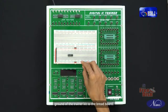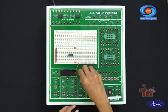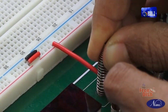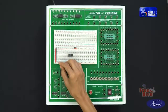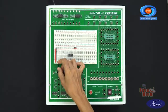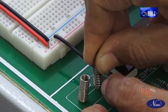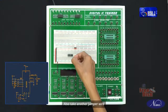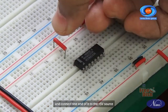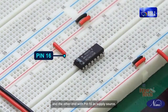Connect the power and ground of the trainer kit to the breadboard. Also take another jumper wire and connect one end of it to the plus 5 volt source and the other end with pin 16 as supply source.